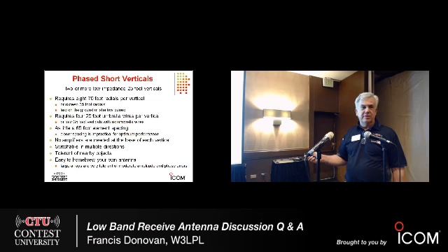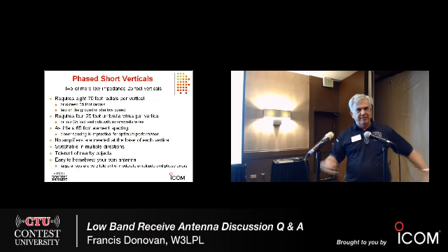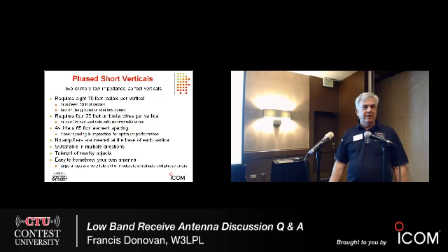Some of my verticals are in a swamp, and some of the verticals are several feet higher on dry land. And it's important that you have enough radials so that the feed point impedance is about the same. I found with my antennas that 8 70-foot radials was adequate. They are randomly laid on the ground. They're not pulled tight. They're not buried. They're just laid on the ground, and that's perfectly okay. I don't think there'd be any benefit at all to making them straight.